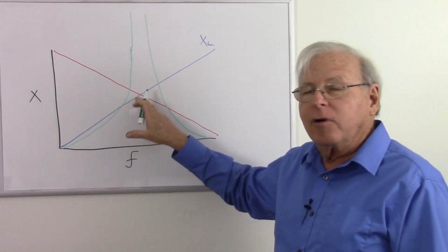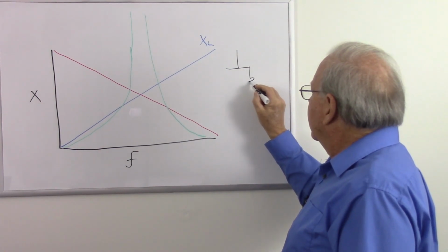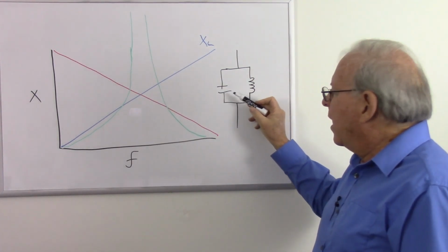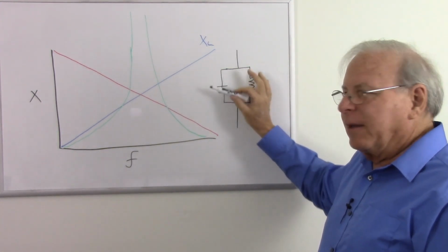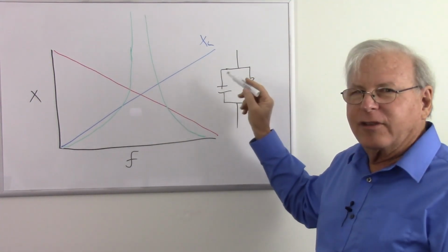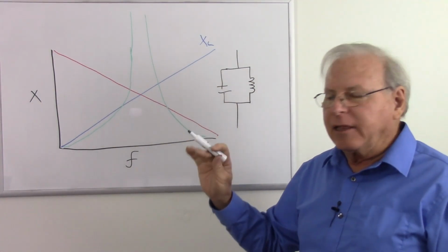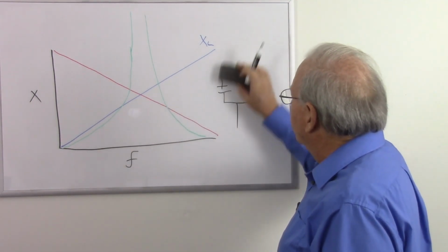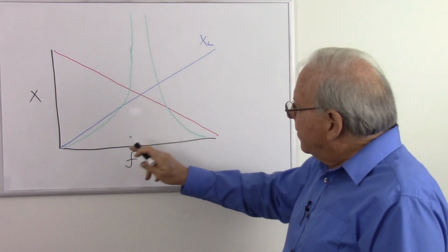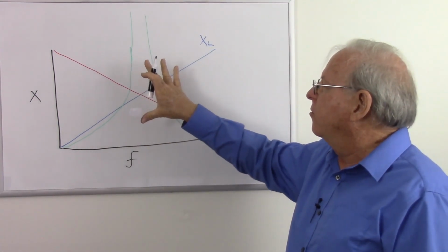And that's one thing I have a real hard time explaining from a conceptual point of view, is why this goes up so high, why it goes up to infinity. Why do I have an infinite impedance when I have two components in parallel where, when one's a high impedance, the other one's going to be low and vice versa? How is that going to become an infinite impedance? Like I said, I haven't found a way to illustrate that conceptually, but I can show mathematically that it will happen. And of course, in the real world, we look at practical circuits and we see that that does appear to happen. So that is what happens to our circuit if we have no resistance in there, as I've illustrated the circuit so far.